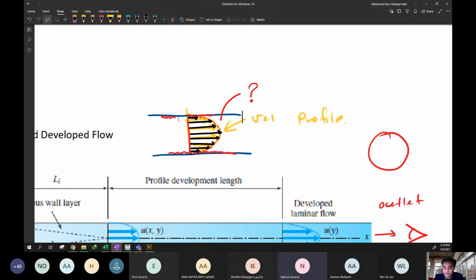The viscosity is constant. Okay, remember that the viscosity is still the fixed constant for the property. But the difference here is actually the velocity. The velocity will be affected by the locations of the flow. Isn't the viscosity between the liquid and the wall one and between the liquid itself, the internal viscosity, different? I mean the intermolecular force of the liquid. So isn't it different? Okay, it is not different. Dynamic viscosity is still the constant.